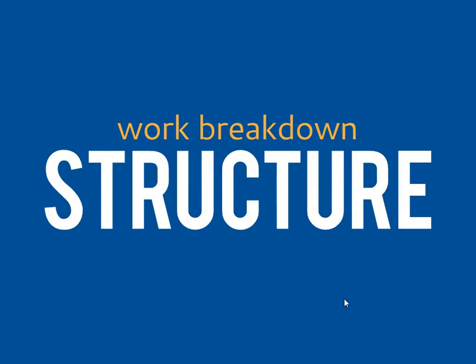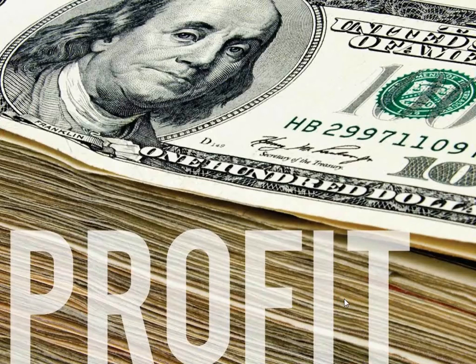From there, we're going to place those pay items into the work breakdown structure. We start to develop costs for the breakdown of items we come up with and attempt to estimate the best that we can the labor, equipment, and materials that we'll need to accomplish each task in the structure. We also want to make sure our breakdown structure includes both direct and indirect costs. From a contractor's standpoint, once we've defined our costs, we're going to mark things up and define our own profit. In HD estimating, it's called the price breakdown.